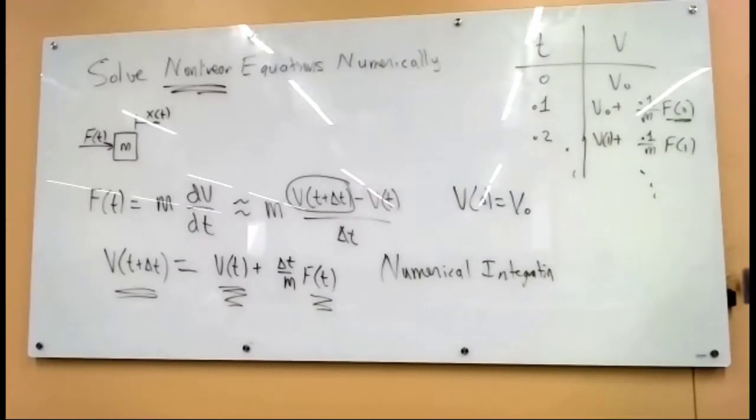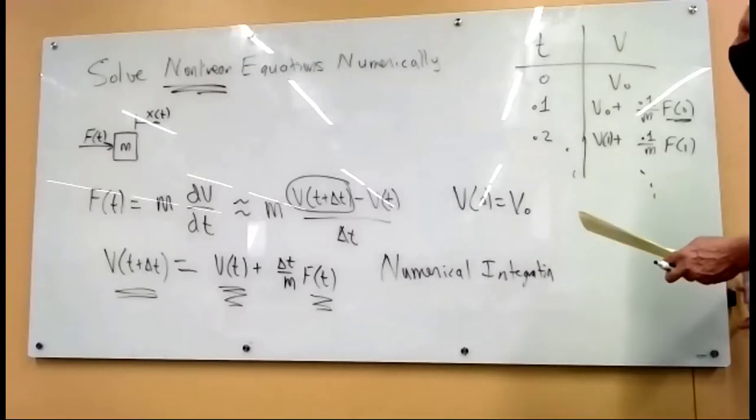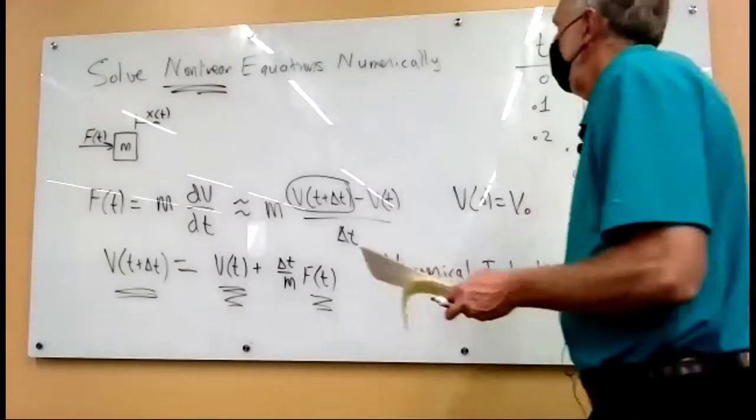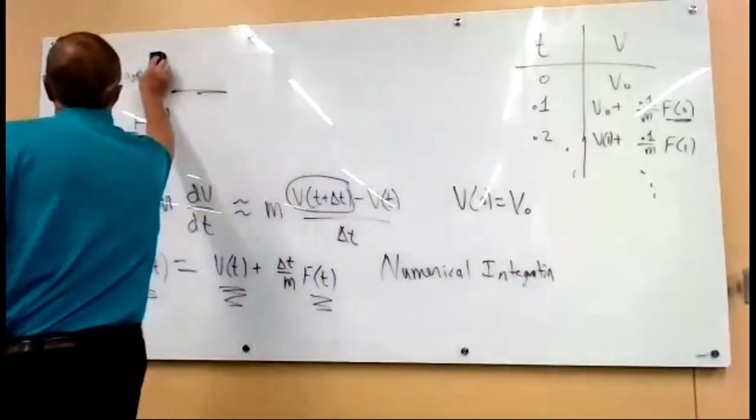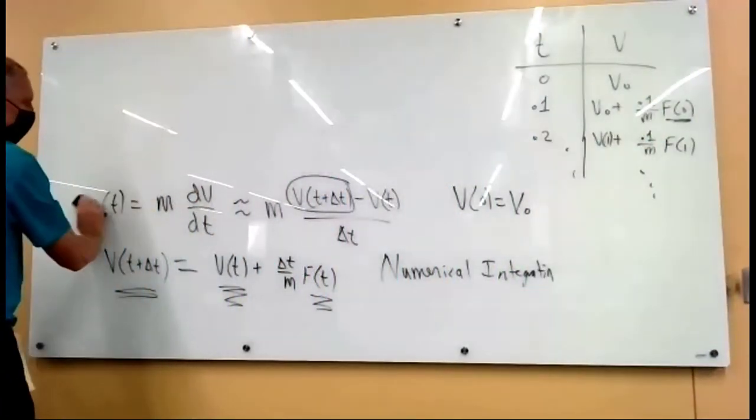And you can do this without a computer, right? You could calculate this. You know your initial velocity, and in 1/10 of a second, the force divided by the mass times the delta t gives you the new velocity. So you can do this with each one of those equations of motion for an airplane. They're no different. They're a dynamic equation. Like the u dot equation, there's nothing new there with what we just did.